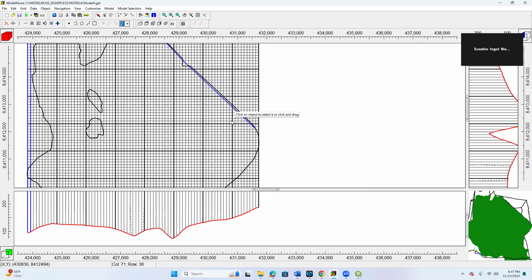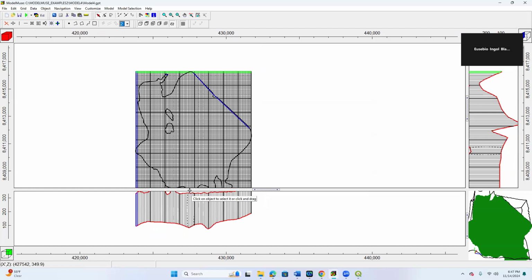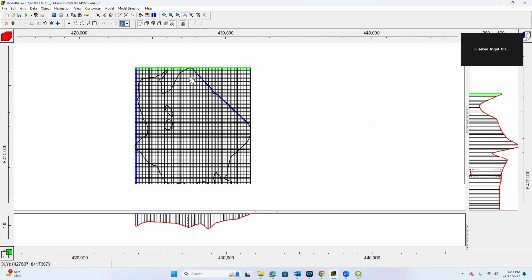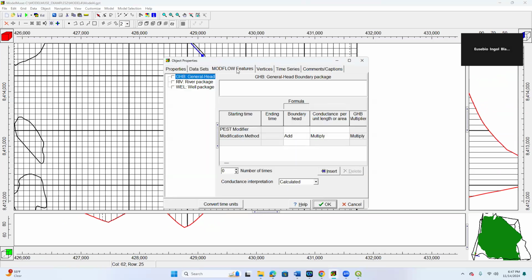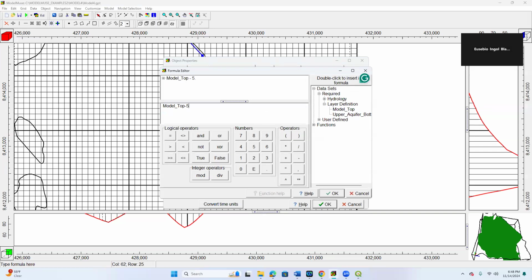You see here these boundary conditions, and then we are going to set up, let me see once again, okay, click over this boundary condition, and then we are going to set up here, select this GHB, general head boundary condition, okay, and then look, select -1 to 0, and then here we are going to use from the model top -5, for example, okay, it's going to start the boundary condition in this case, okay, and then click here, model top -5 meters, for example, and then